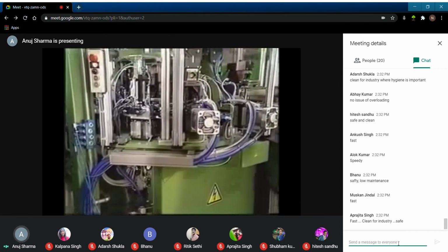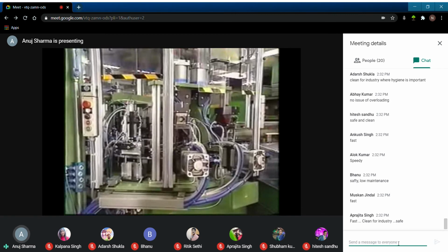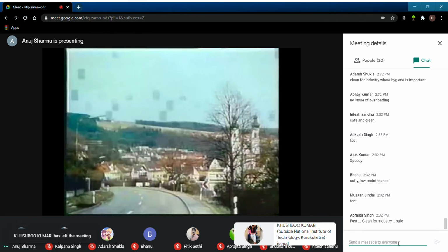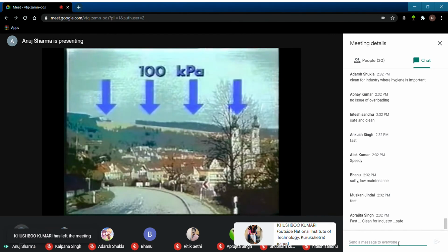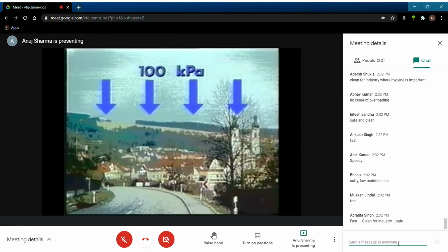A few basic principles of physics enables you to gain a better understanding of pneumatic systems and how they function. Let's start by defining pressure. Atmospheric pressure is present everywhere on Earth. It's generally regarded as being a constant at sea level of 100 kilopascal, abbreviated kPa.